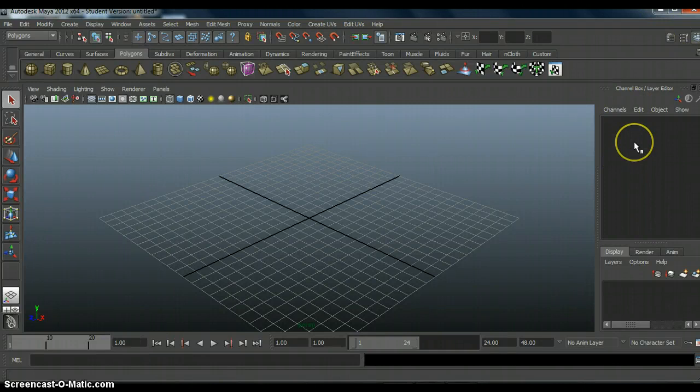On the right side, we have three options available to fill this area. Those include the attribute editor, tool settings, and channel box. We will focus on the attribute editor today, and what it does is it manipulates settings for an object. Over here in the viewport is the main area that you will use to interact with objects in a three-dimensional or two-dimensional space. These objects include polygons, NURBS, and subdivisions.